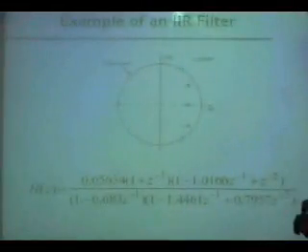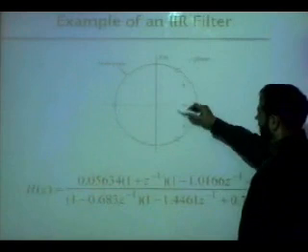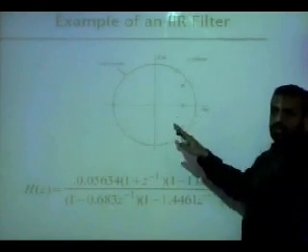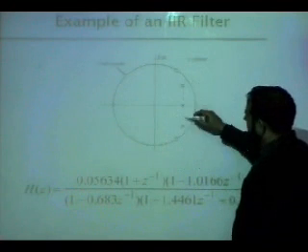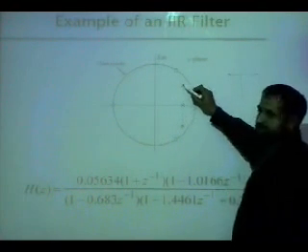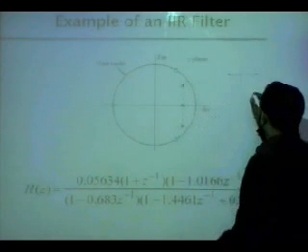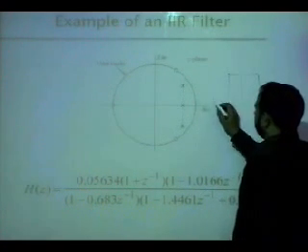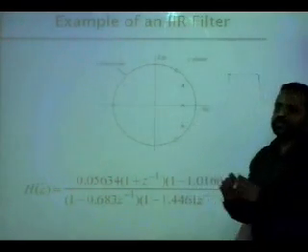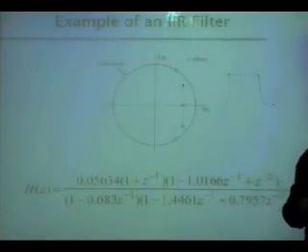We will learn about algorithms that place poles automatically, in a fashion such that the frequency response remains flat from 0 to this frequency, and then it will dip. The placement of the zero here will bring the frequency response down as quickly as possible.